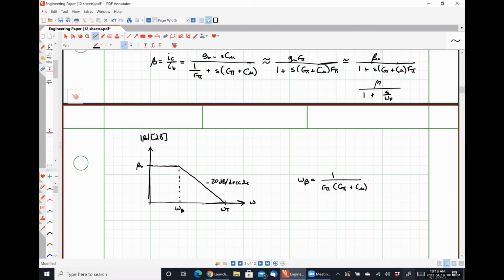Now, we're almost done, I promise. This is an amplifier. It's a real amplifier, right? We are measuring the current gain of this amplifier. If this horizontal axis represents 0 decibels, then this frequency, omega t, is what's called the unity gain frequency of our circuit, all right?